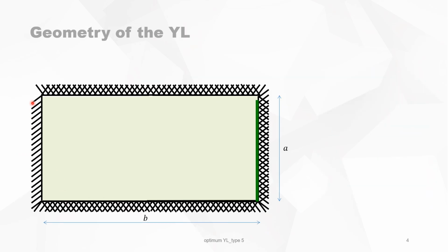Using yield line theory, we know that the rotation axis of the different pieces of the slab will rotate about their support, and we have four rotation axes. And when two rotation axes cross, then the yield line starts at the cross point. And it starts with an angle beta 1. So for each corner, there will be a yield line that will start.